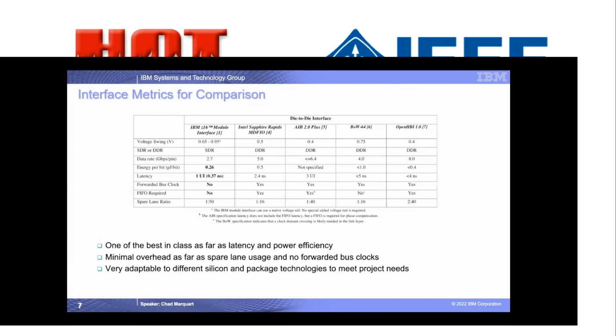Finally, this interface is very adaptable across numerous CMOS and package technologies. The simple architecture used for this interface can be implemented in just about any modern CMOS technology. The implementation of the individual drivers and receivers as both power and area efficient autonomous entities really enables scalability that is almost limitless. Some of the most significant constraints to scalability that should be considered when selecting a package technology are the C4 count, the C4 pitch, and the impact that the combination of those two have on the maximum interconnect length through the interface.